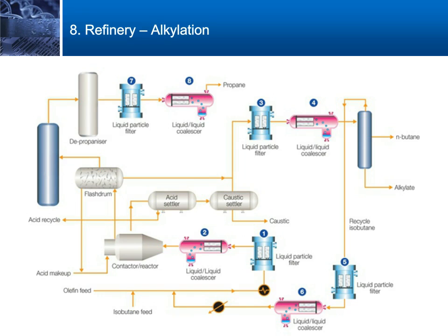Flow passes up and out the top and then down to the bottom right. We can see housings 5 and 6. There's a recommended placement here of a coalescer to handle large volumes of recycled water. With the recycle isobutane stream, you can have in the range of 1 to 3% water levels on this stream commonly seen.